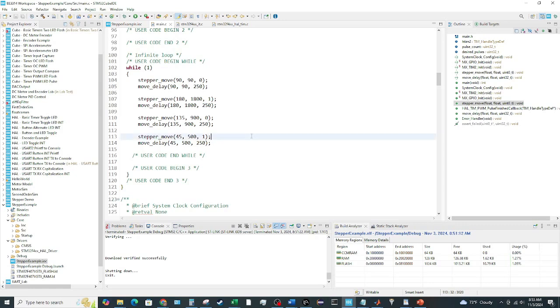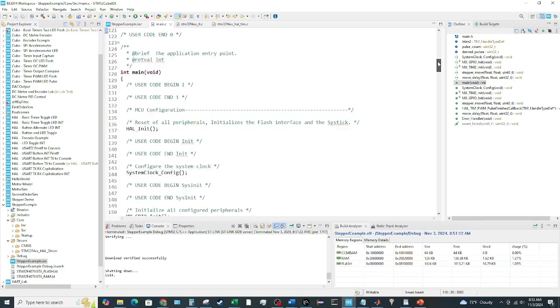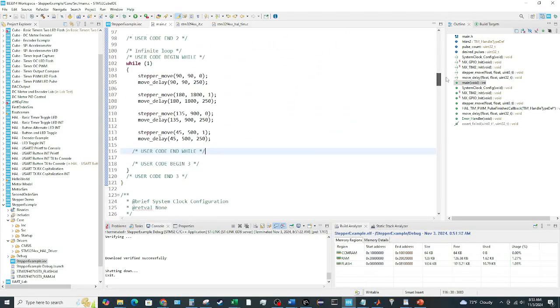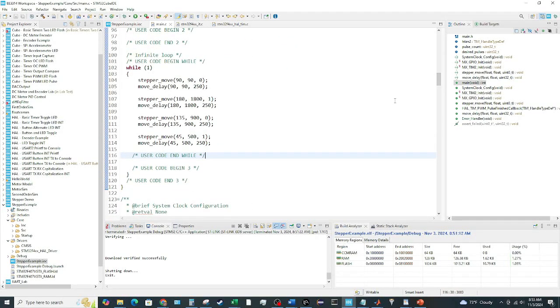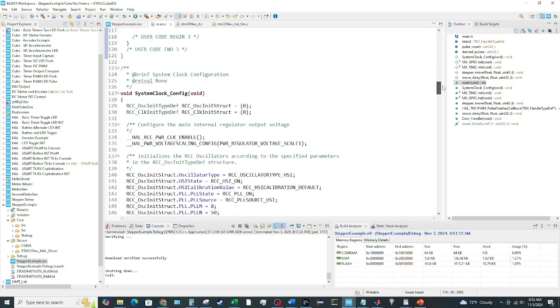Okay, so hopefully that was useful. Just one example of one way to do stepper motors. There are other ways to do this. The timers do have what's called a one pulse mode, and you could just tell the timer to go issue a pulse. That's another way to do it instead of having it pre-run in PWM mode and then counting those pulses. This is a little bit more straightforward to me, and also is an extension of what we've already done in PWM mode. So that's why I use this particular method.